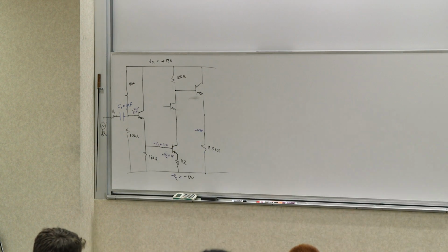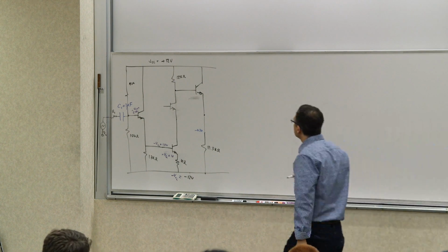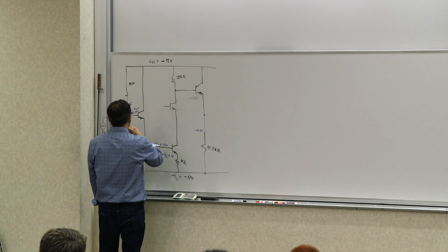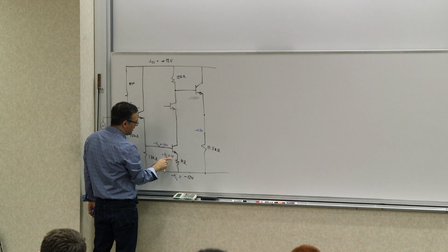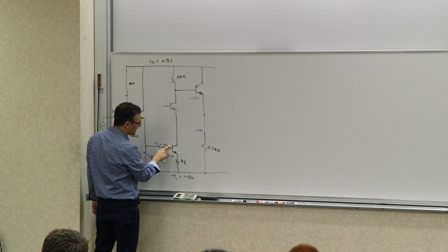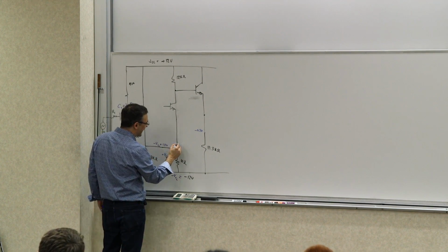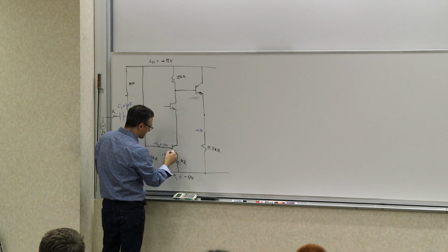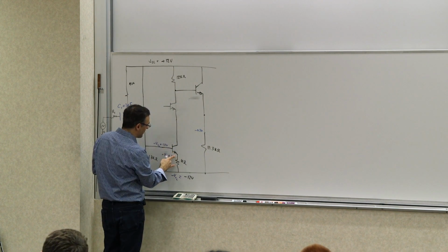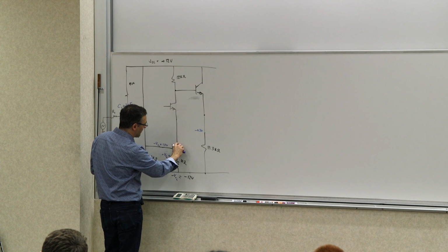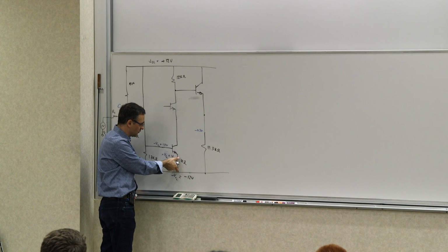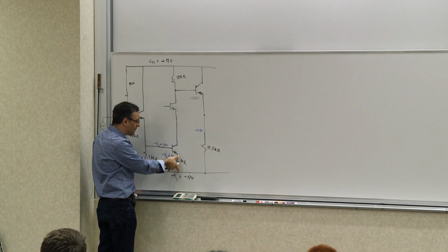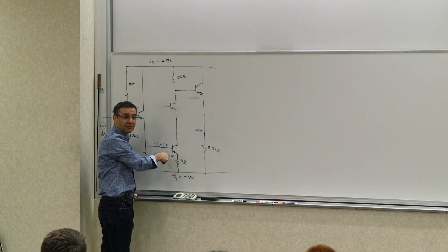You can do it any way you want, just like I picked a 10 and 85. Basically I'm going to keep it a little bit above 2.4 volts, where this becomes 1.7. So this voltage is 1.7. This voltage is 1 volt. So if the current was 1 milliamp, this can go down to 1.2 volts above this voltage, because it's 1 volt here. But that will happen at a higher current for this to be pulled down that low.